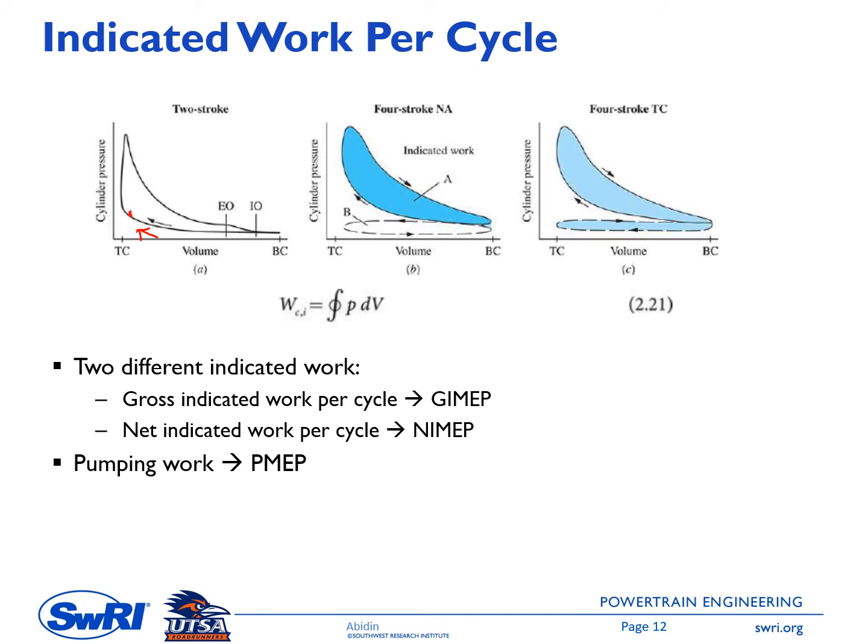And then there will be an expansion process, okay, expansion stroke, and then at some piston position, the exhaust port opens, so there will be an exhaust process, okay. The gas exits the cylinder because of the huge pressure difference between the cylinder and the exhaust manifold.